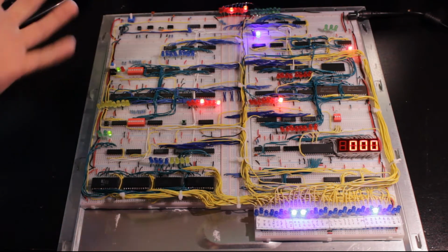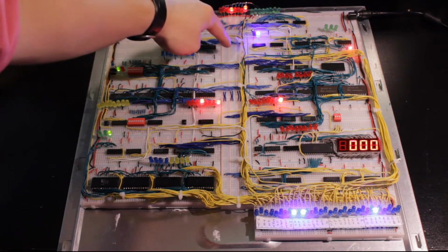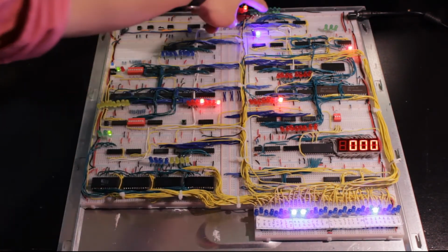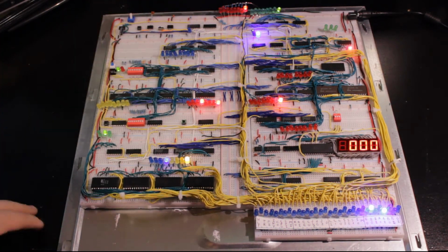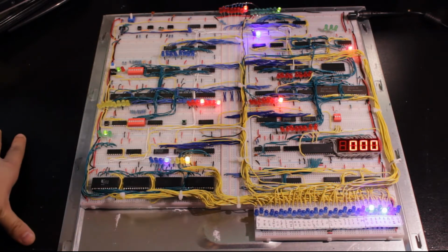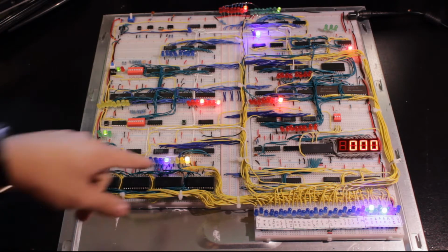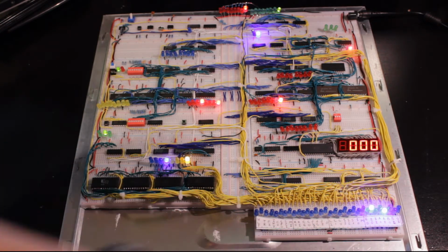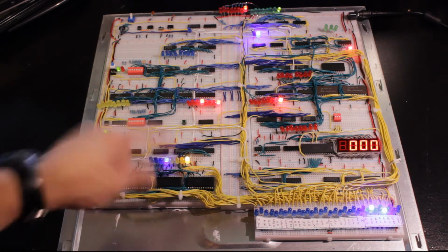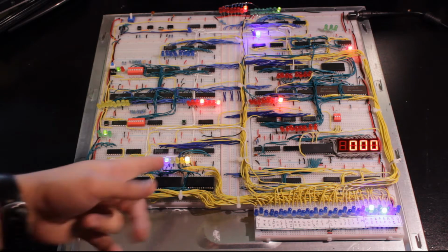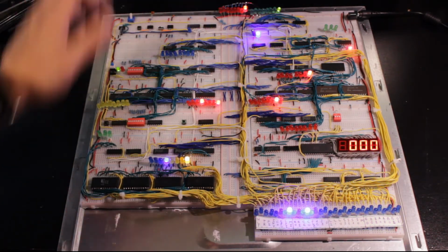Nothing exciting here. And we just advance to the next T state, where we're going to take the RAM out onto the bus into the instruction register, and we're going to enable the counter, so this is going to increment by 1. So now we're done the fetch cycle, and we're actually executing the load immediate A register value of 1. So we're taking now the instruction register out and the A register in. We take the least significant 4 bits of the instruction register out onto the bus, so we have a value of 1, and then that's going to go into the A register on the next clock cycle.